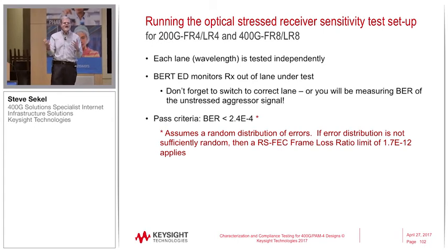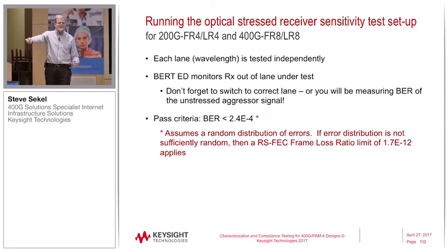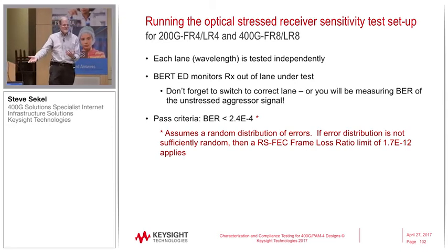And you just run that mechanism for the entire test, and then you count at the end how many bits went in, and from that you can mathematically determine how many frames went in, and you determine how many of them would not be correctable by Reed-Solomon.